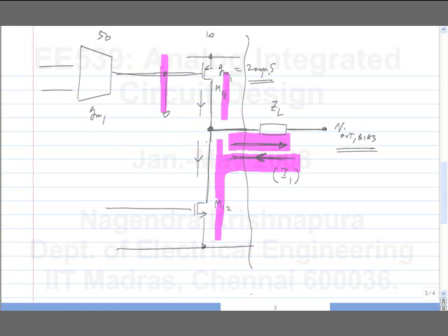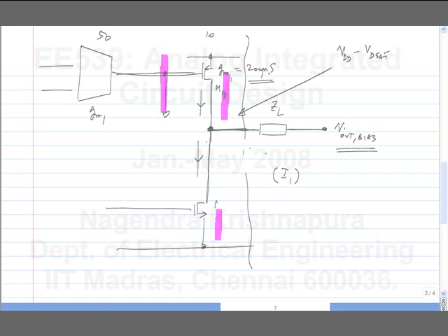So in our particular case, let's take only the resistive load. What is the swing that is possible here? What are the swing limits of a two-stage amplifier? It's approximately VDD minus VD sat 11 on the upper side, and on the lower side it's VD sat 12. I say approximately because as this voltage is rising up, this voltage is falling, right? So you may have to take that into account, especially when you have a second stage with a very low gain, let's say a gain of 3.